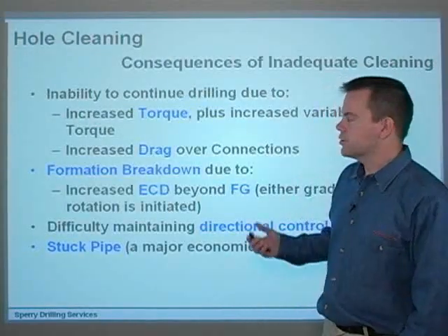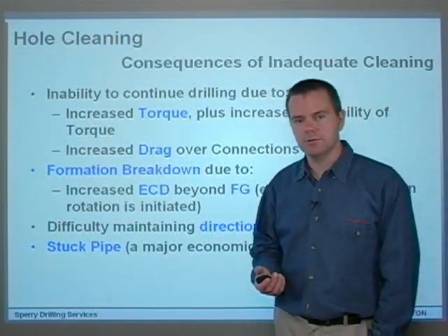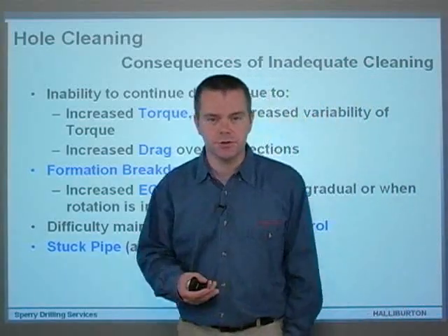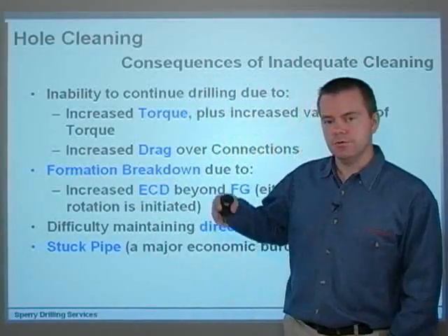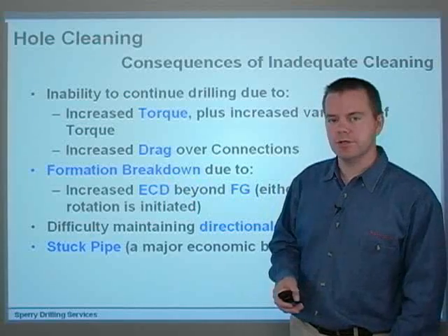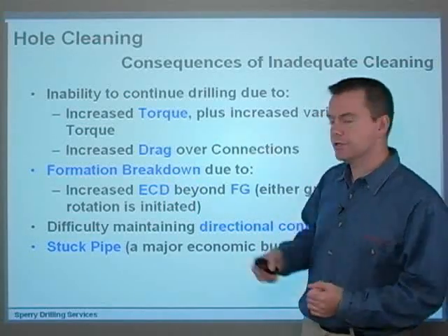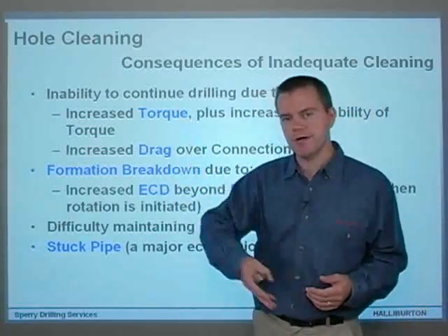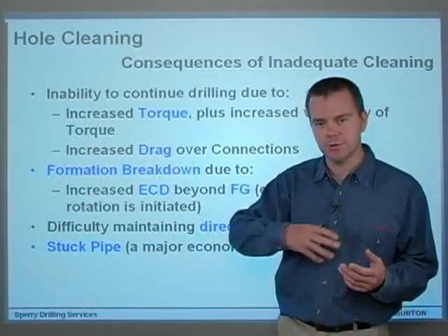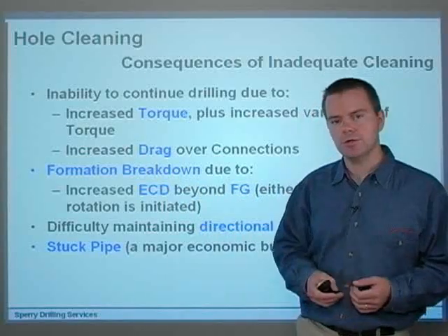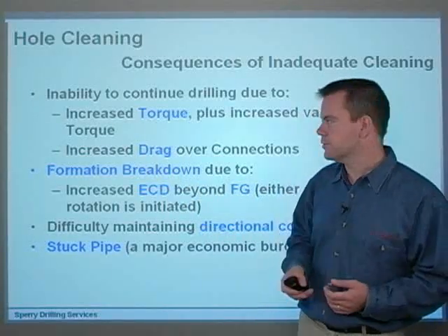So what are the consequences of inadequate hole cleaning? Well, basically, there's an inability to continue drilling. If you don't do anything about it, you won't be able to drill any further because the torque will increase too much. You'll also probably increase the variability of the torque, or how erratic that torque is. So you'll have a big fluctuation in torque. It could lead to stick slip as well.